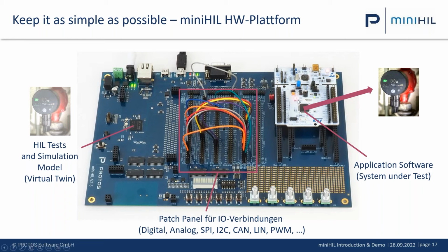And what we do is now we connect the pins of the microcontroller over this patch panel with the test system, directly or indirectly. And by doing that, we can run here all the needed environment simulation, the bus protocols and the test cases and so on the test system.